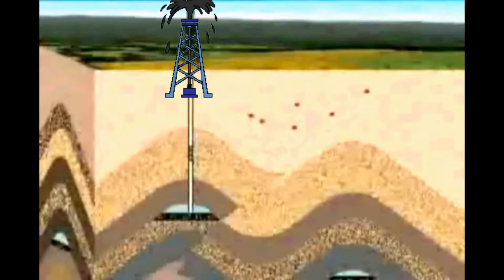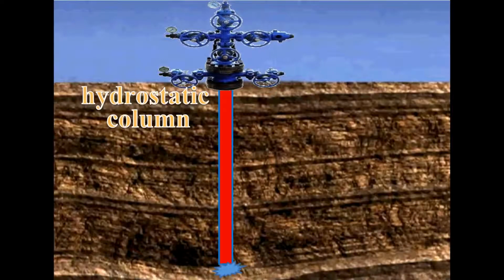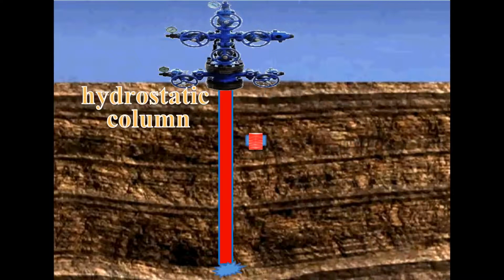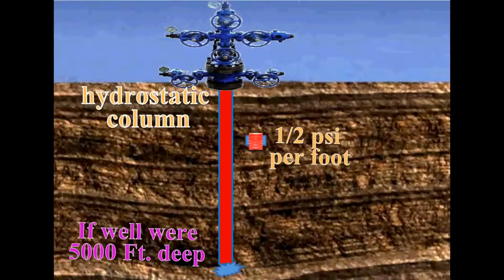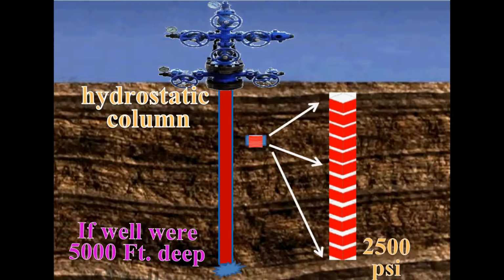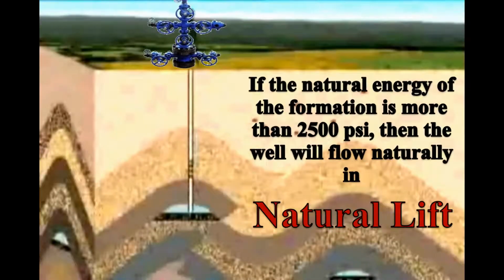In this illustration, you see a hydrostatic head of a fluid column that stretches from the surface to the reservoir. As the column deepens, psi increases about 1/2 psi per foot of reservoir depth. So, if this well were 5,000 feet deep, for example, the psi at the bottom of the well would be about 2,500 psi. If the natural energy of the formation is more than 2,500 psi, then the well will flow naturally in natural lift.